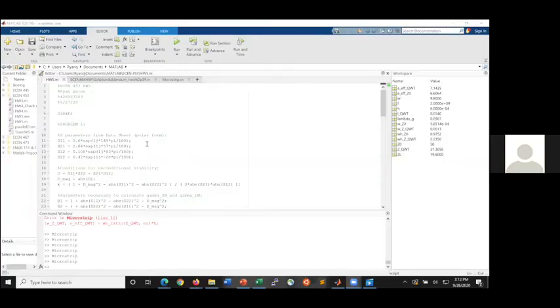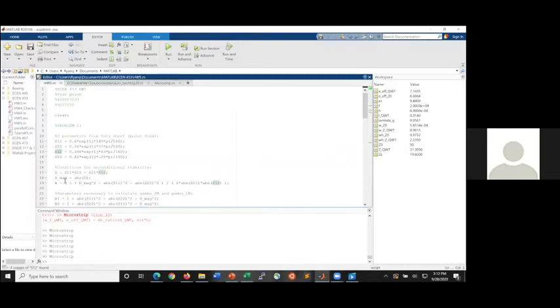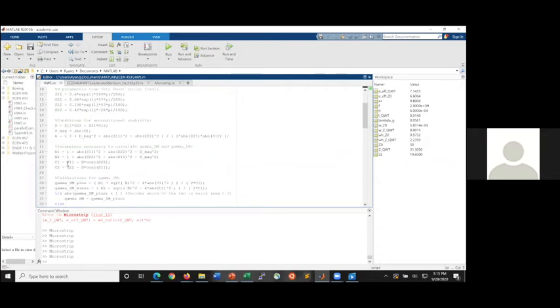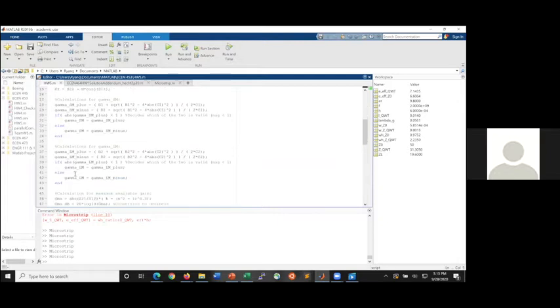I could share my screen and show you the code that I have. It's basically just all the equations for the analysis. So I'll share my screen here. Can you see it? Yes, I can. So I just put the S parameters in, calculate D and K, I got the B's. I just plugged all the equations in. Here's gamma, that's for the matching network.